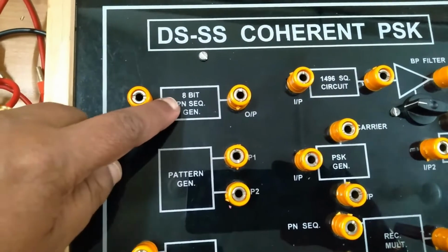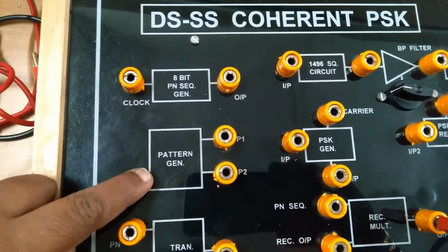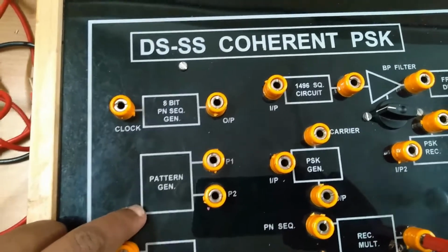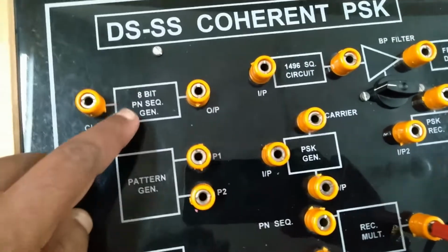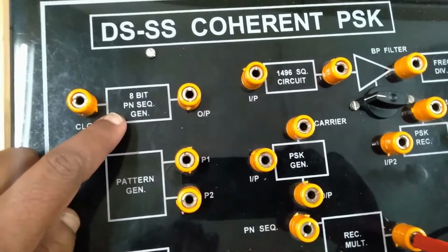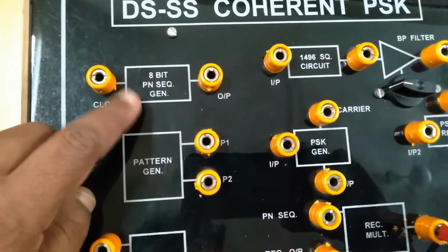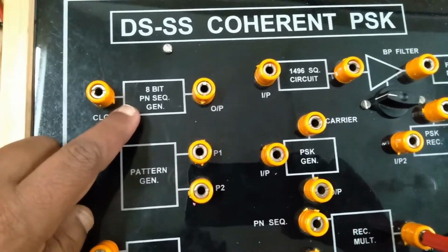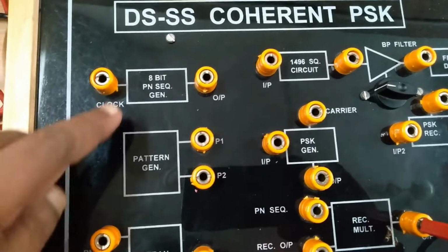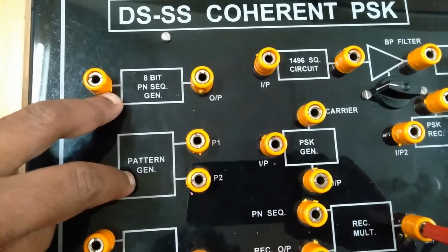If I add this particular PN sequence to my pattern, then those receivers who know the PN sequence can regenerate your data back again. So it's acting as a security code for the data which you are transmitting, right? There is a technique where we have a 6-bit, 4-bit, or 8-bit pattern generator. We have a different practical setup for the generation of 8-bit also. So just remember that this is a security code for keeping your data secure, that is, transmitting the data in a secured way. Your digital data with the help of the PN sequence is going to be transmitted.